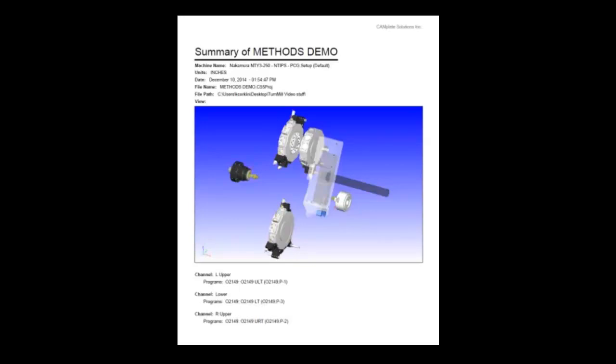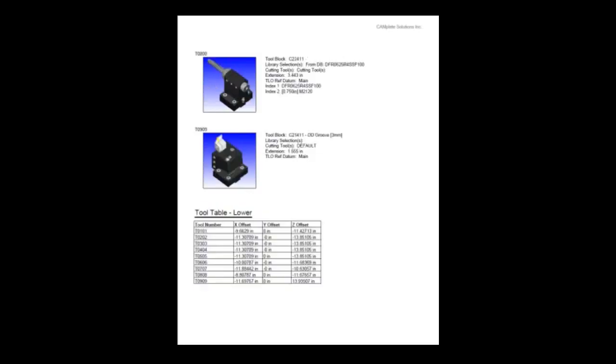That gives us an overall summary of the job. This happens to be a 3-turret twin spindle machine, 2 upper, 2 lower. They all have Y-axes. And we did a demo job on it. The data that it gives you on all the tools is very good. It gives you the tool number, the tool holder that's being used, the tool itself, even the insert if you need it, what spindle it's facing towards, and the tool length offset. And it does that for every individual tool.